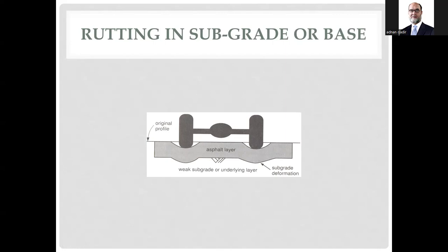Now the problem is, even though the asphalt layer was very good and your base layer is very good, you have to throw all of them out. This is more of a disaster than the first one. In the first one, there was failure in the asphalt concrete. Yes, you removed it, but your base and sub base were okay, so you compacted that. But here, you have to remove even the other layers. There's nothing wrong with them. So estimating the subgrade strength is very important.